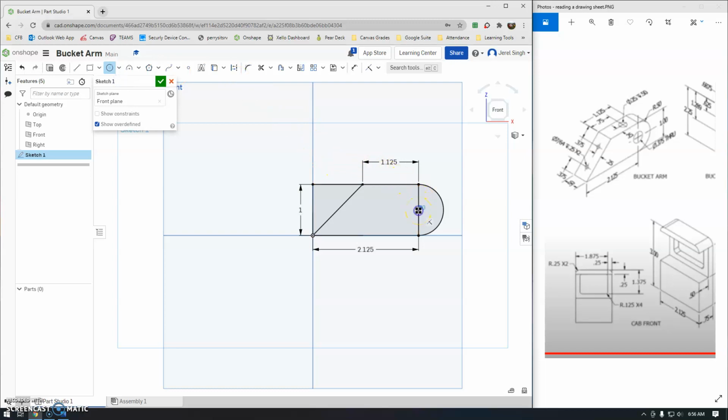I'm going to click this center dot, move out. Again, it doesn't matter where I click because I'm going to manually type in 0.375, enter. And that's awesome. We've got everything that we want from this sketch set before we extrude. And oops, I accidentally right click there. I'm going to click my green check mark.